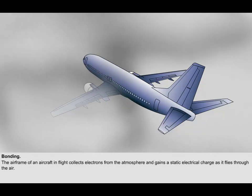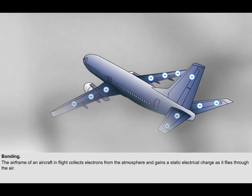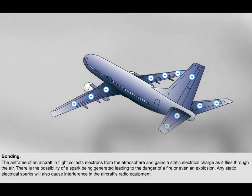The airframe of an aircraft in flight collects electrons from the atmosphere and gains a static electrical charge as it flies through the air. If different parts of the airframe have different levels of static electrical charge, then there is a possibility of a spark being generated between them, leading to the danger of a fire or even an explosion. Any static electrical sparks will also cause interference in the form of static noise or crackling in the aircraft's radio equipment.